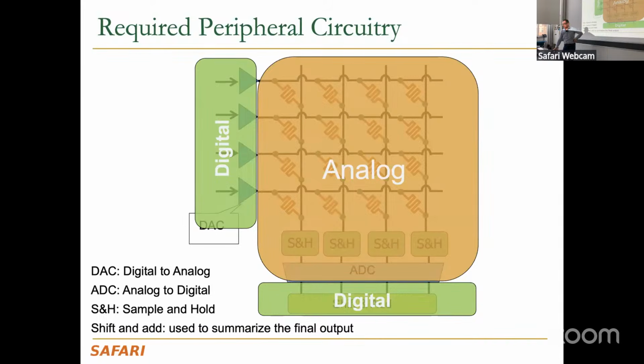You're not building a multiplier, right? We did not build a multiplier. We're just taking advantage of the analog operational properties of the circuitry to do multiplication. Very similar to what we have done with DRAM, right? Except I don't know how to do this in DRAM. If you come up with a way of doing this in DRAM, that could be golden. It may require changes to DRAM, actually. I think it will require changes to DRAM. But if you can find a way of doing this with low cost in DRAM, then that could be golden. There's a thesis topic for some people.